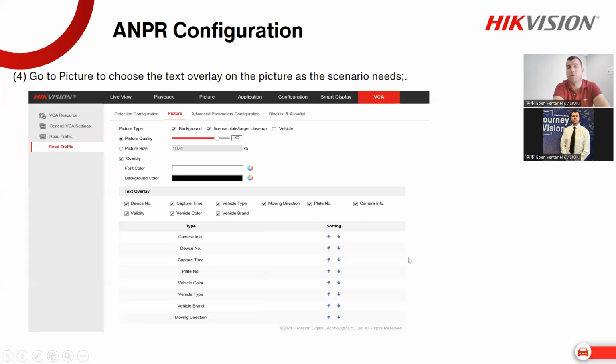You're just basically focusing on the number plate and stuff like that. Not just that, there are also different settings on the image that you can play around with, not just the image, the recording itself, to make sure that you maybe push it up to 25 frames per second and make sure you get the best quality out of your ANPR. That will give you a better quality of image as well.